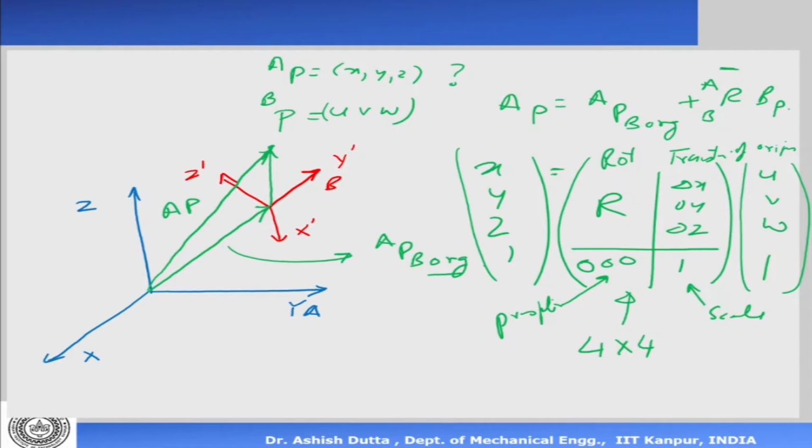So far, we have said that this is an axis system or this is a frame and this is XYZ axis and just rotating and things like that. But then how do we assign this axis systematically in a robotic system? And that is something which we'll see now, and that is what is called axis assignment as per DH notations. DH stands for Denavit-Hartenberg notations. Now, in this DH notations, basically we are going to systematically assign the axis.